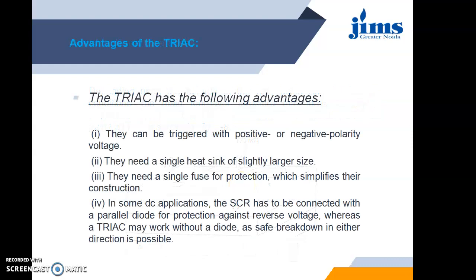So after this construction and its features, which are almost similar to SCR, where it is working as 2 SCRs connected back to back, it therefore shows the conduction and VI characteristics in both forward region and reverse region. We would like to now mention the advantages of Triac. The first advantage is that they can be triggered with positive or negative polarity voltages. The second thing is they need a single heat sink of slightly larger size.